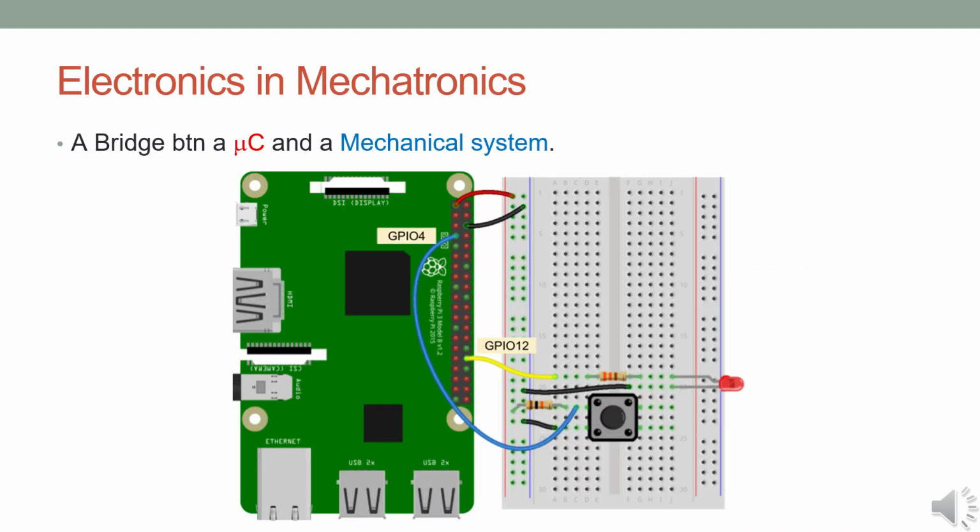A microcomputer is of limited value if it cannot interact with external devices. To be truly useful, it must be able to send commands to external components and receive input from them. When developing systems with a microcontroller or microcomputer, it's essential to understand how to interface with external hardware. In this example, we use a Raspberry Pi, which provides a set of GPIO ports, short for General Purpose Input/Output. These ports allow the Raspberry Pi to communicate directly with sensors, buttons, LEDs, and other devices.